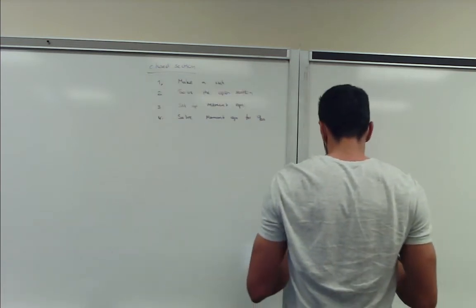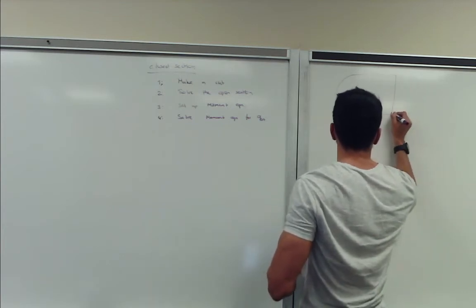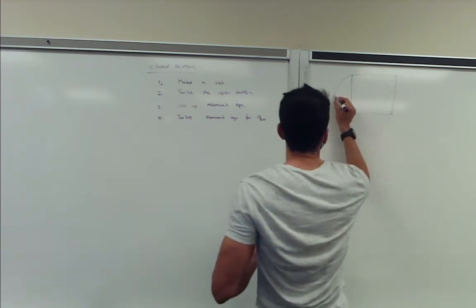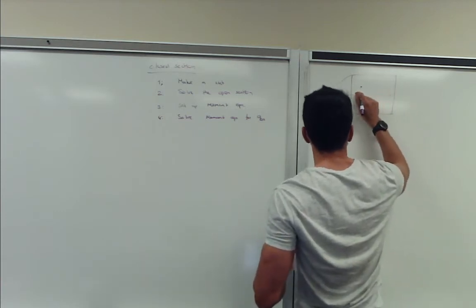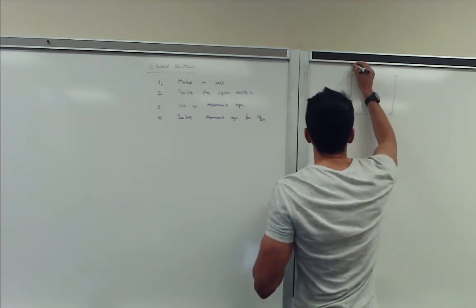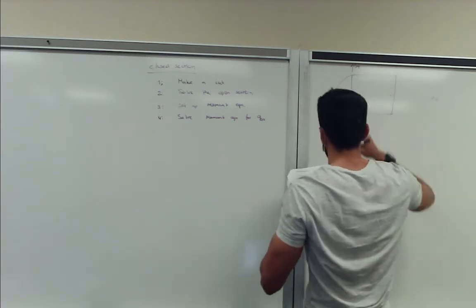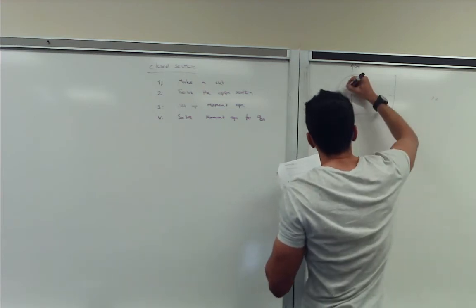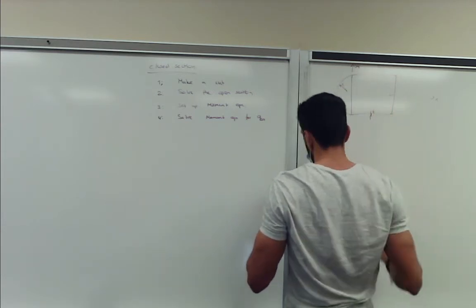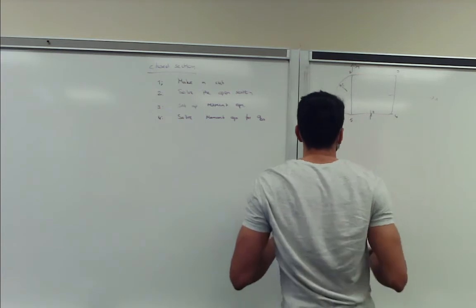Okay. So we have the following cross section. It's a closed section. It's a pointed box, say a box with a cone on top on one side. The shear force is acting on the front spar, and this is our x-axis, and this is also our y-axis, and this is radius r. The thickness is t everywhere, and we define points 1, 2, 3, 4, 5.